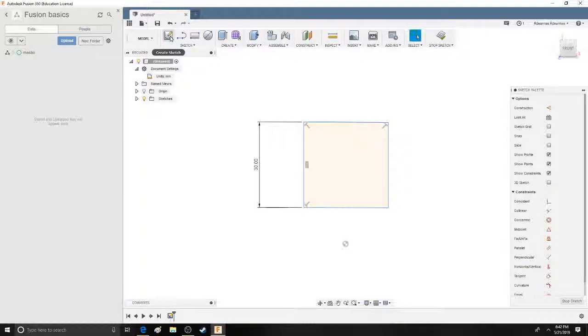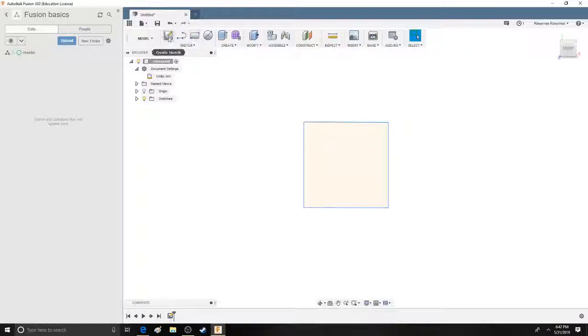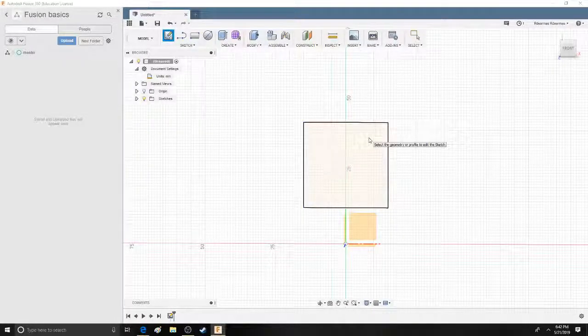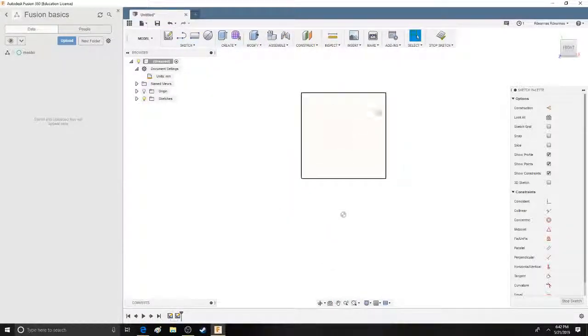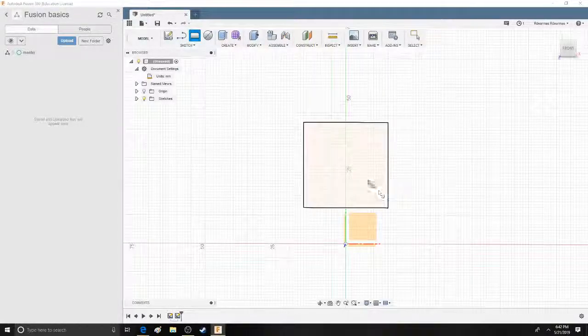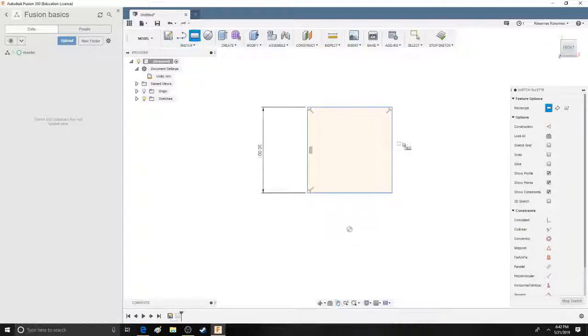Let's move over. So create sketch. I'm going to stop the sketch right there. Create sketch just instantly puts you into the create a sketch mode. It also allows you to select certain sketches to work back on them without having to select a tool for it. So instead of clicking line, you can create sketch and instantly edit what you have with that sketch. As well, you can move over and do a 2-point rectangle. I'm going to click on this. You can do it on other planes.